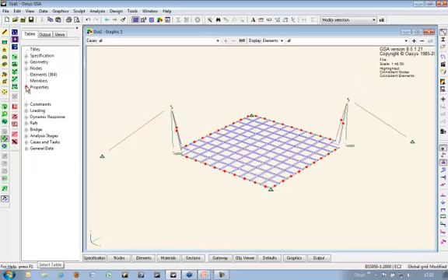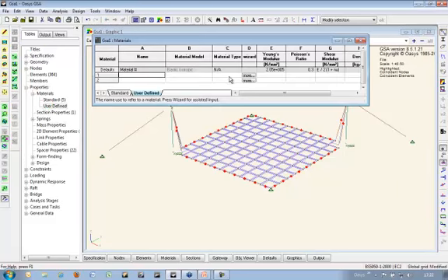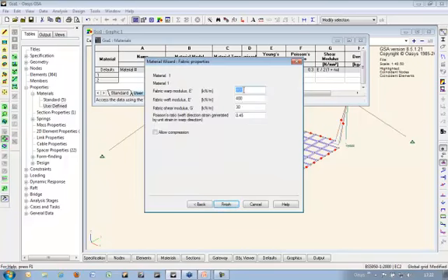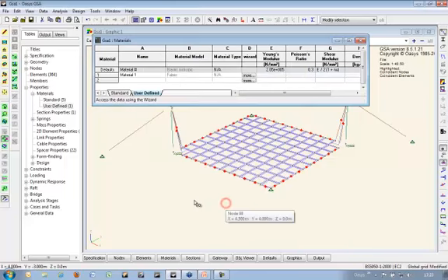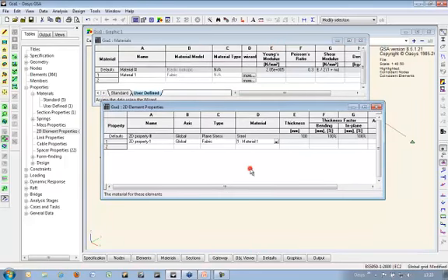We also need to set up material, so our fabric material. I'm going to use defined material, and I'm going to say it's going to be a fabric. And for these warp and weft factors and so on, speak to your fabric manufacturer. These are just some defaults. And the properties themselves, still 2D element properties, I'll need them to use this fabric material.